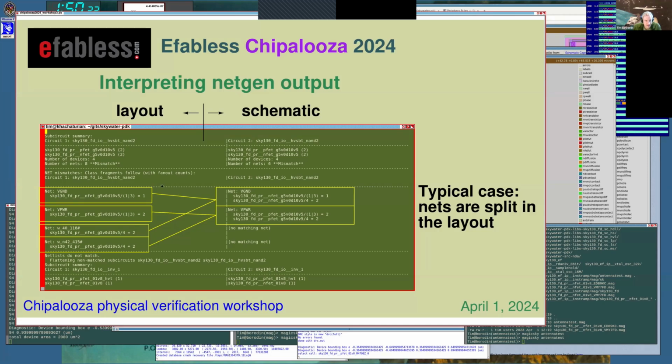Over here, those are split into 2. So I've got my V ground net is connected to a NFET source or drain, but the bulk terminal here for 2 NFETs is connected to some other net. So that tells me immediately that over in my layout, I have got a floating well and substrate that have not been tied to my power and ground.